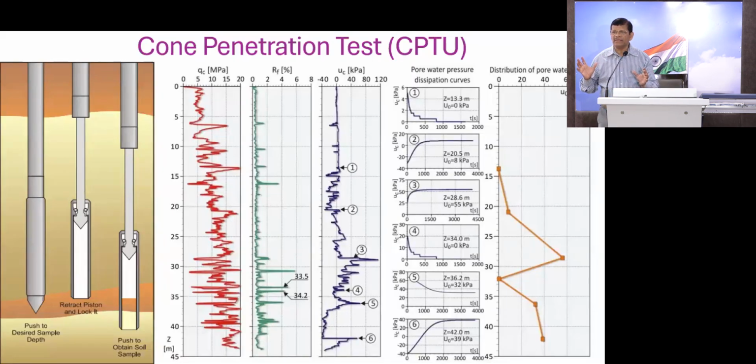Normally when we initially started, we followed the same principle. We thought tailings is a soil, so in soil we have experts, and we go and do the SPT test to find the N value, and anything we can design using that. But when people saw that in tailings it's not giving much information, yes, the N values are low. But what are these low N values telling us? Whether this dam can be used or cannot be used.